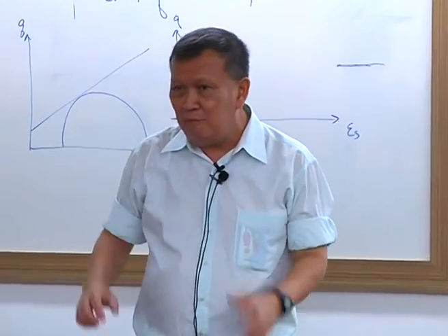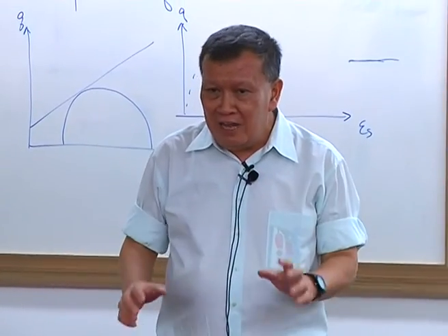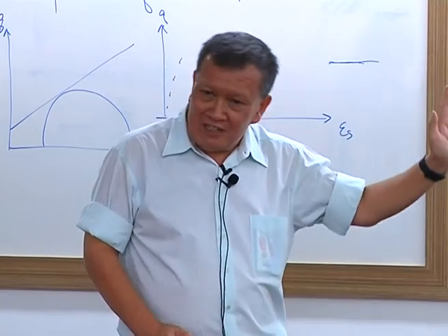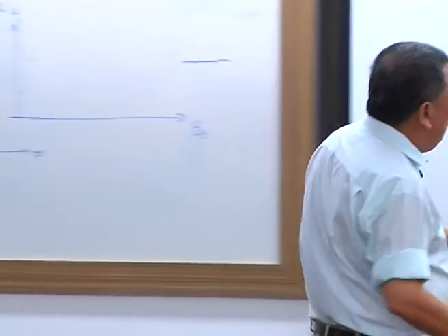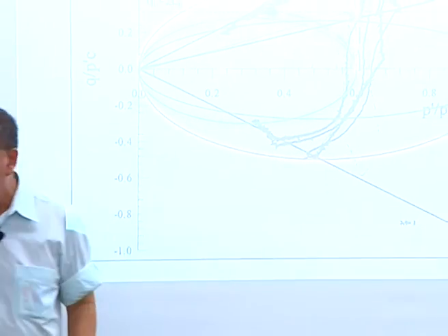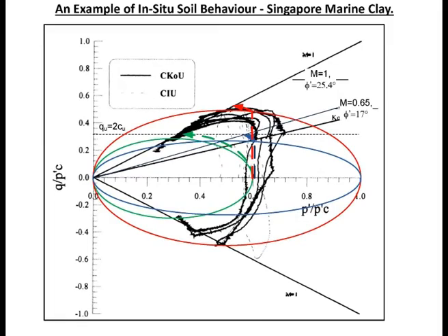The vertical stress path for a structured soil. For a less structured soil, you probably get the thing turning back, the classical leftward turning stress path this way. But this is a structured soil, sensitivity of about 3. You can see that there is actually an effect of the structure coming out.